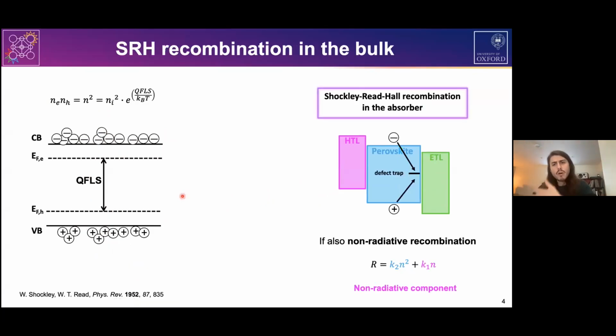limitation. Now, in a more realistic scenario, our semiconductor will have some defects and traps, which will act as non-radiative recombination centers. These will act as an additional non-radiative recombination path, which will further decrease the density of electrons and holes in our system. As a consequence, it will reduce the splitting of the quasi-Fermi levels. Hence, we will have a lower VOC.